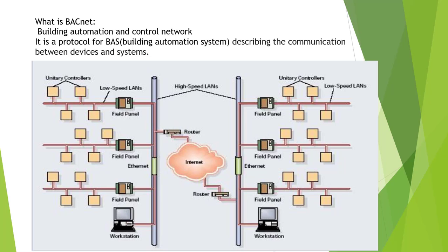It's a protocol for BAS, describing the communication between devices and systems. Look like this. Use a router. It's one system communicating with another system. Use BACnet IP. This way, device controllers and all the panels communicate.